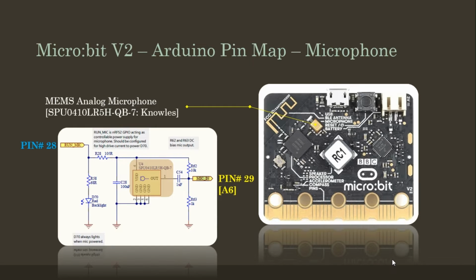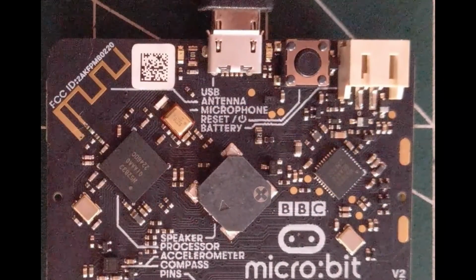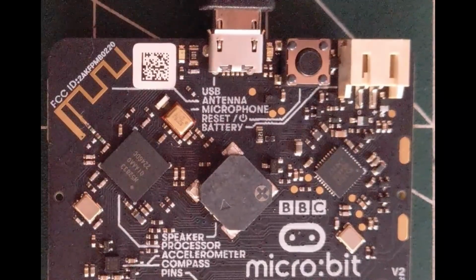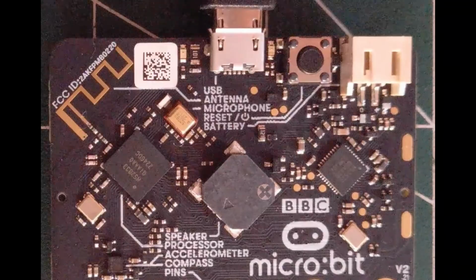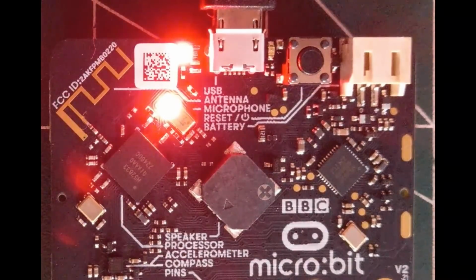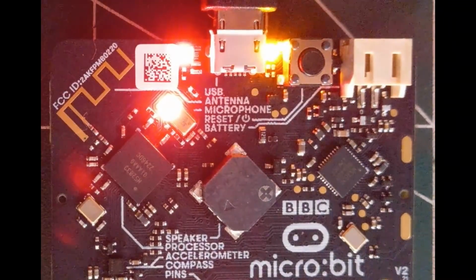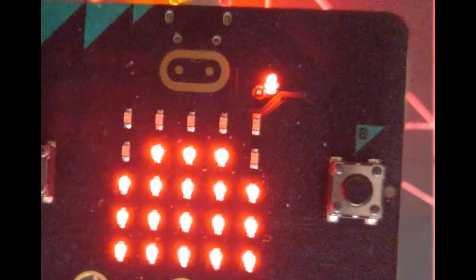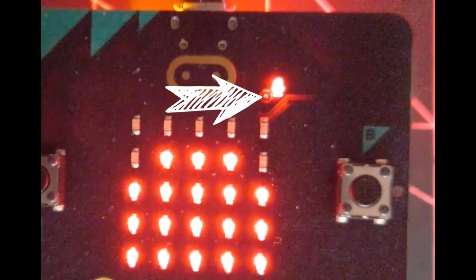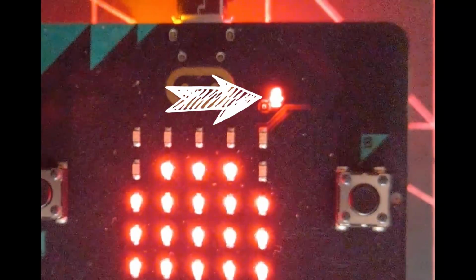If you're not using the microphone and want to use the mic in signal as the digital input, use port pin number 29. Enabling the run mic signal will not only provide power to the microphone but also activate an LED, indicating that the microphone is on. It's important to note that the LED indicator is visible from the other side of the board where the microphone is mounted. Additionally, there is a hole located at the bottom of the microphone, which can be accessed from the other side of the PCB through the opening on the PCB that aligns with the hole.